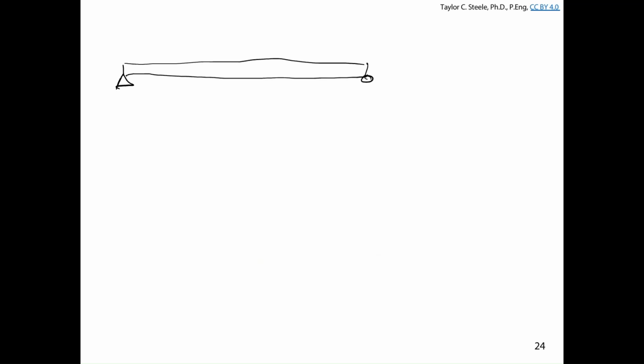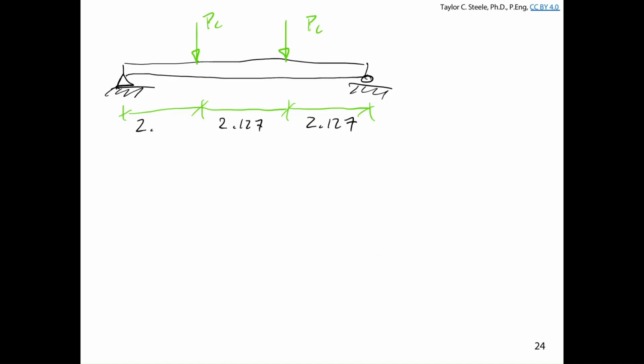It's working like this. Let's just assume for the girder calculations that the partitions will be permanent. It's not compatible with the joist calculations, but let's assume that we made a mistake there as the junior engineer, and that will shorten the example a little bit. So in that case, we're going to have some point loads from the live load, right? Point load, live load. And they're spaced at the center to center spacing, which is the same as the tributary width for the joist. That's, why do I keep writing 3 instead of 2? 2.127, 2.127, 2.127.